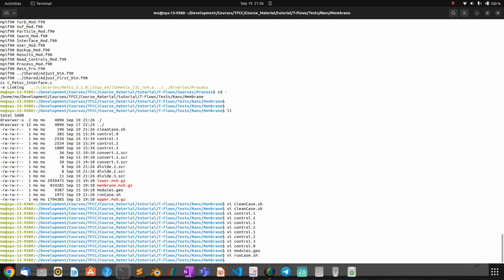Here there is a small difference to the previous cases, and I actually updated the source on GitHub, so you can have the same feature again, or you have both features, but since I updated this run script, you can have it in a smoother way than we did in the last session. So what changes is that you run the case like this, and once you run it, you wait until the mesh is converted or extracted, and then you pass the word serial or parallel, so you can tell the code in which mode it will run the process, so that you're not confused.